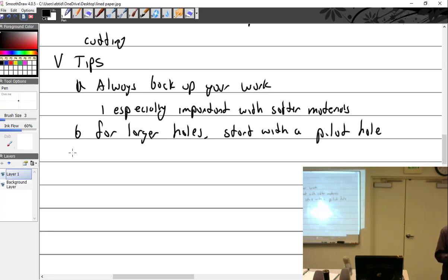And then, now according to the guy in the video, you want a pilot hole just big enough to get your chisel point in. Now, if it's thick enough and strong enough, I'll go 1/8 inch, then I'll pick something in the middle, and then I'll pick my final. I'm going to do 3 or 4 holes to get all the way up to 1/2 inch because, man, it's a lot of work.